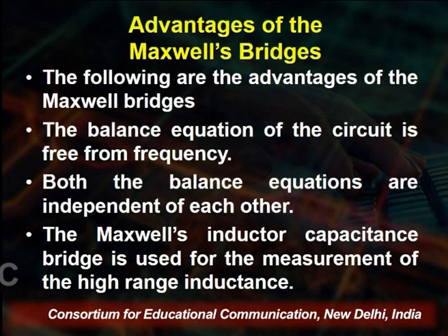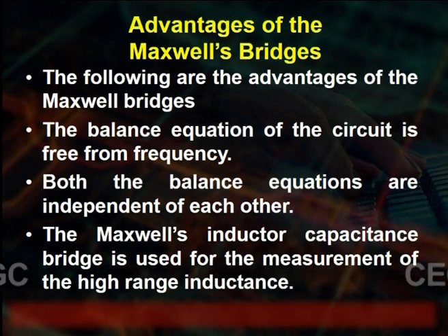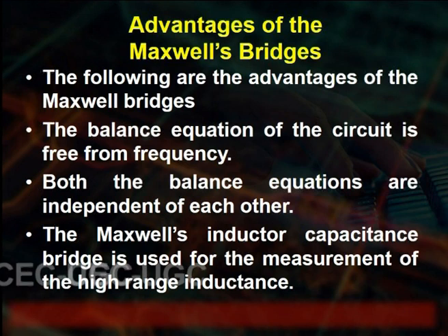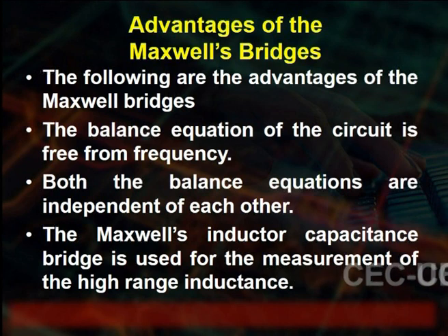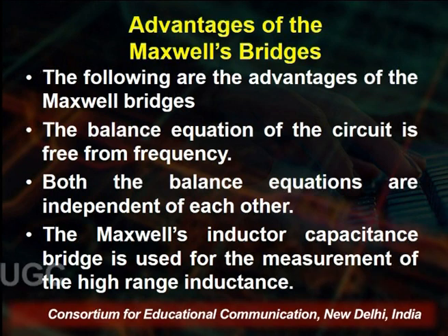And what are the advantages of the Maxwell bridges? The Maxwell bridge has the advantage that it is used when the balance equation of the circuit is free from the frequency. Both the balance equations are independent of each other, and as we see, the frequency is not required here. The Maxwell inductor capacitance bridge is used for the measurement of the high range of the inductance. We can measure the high range of the inductance.